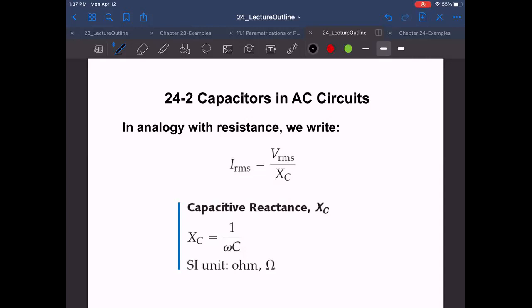We typically use this, say I had a speaker here, and I had my source over here, my radio, and I wanted this speaker to ignore any of the high frequency signals. So say this is a subwoofer. What I would do is attach a big capacitor right here.